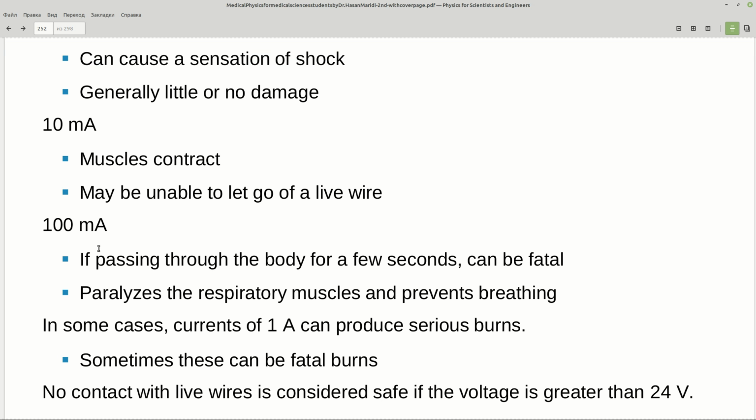If this line with the live wire is accidentally shorted to the casing, the most of the current takes the low resistance path through the appliance to the ground. So the current, like a river, is trying to find the lowest resistance path to go, and it finds some way. The most of the current takes the low resistance path through the appliance to the ground.